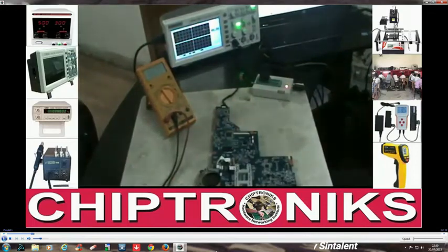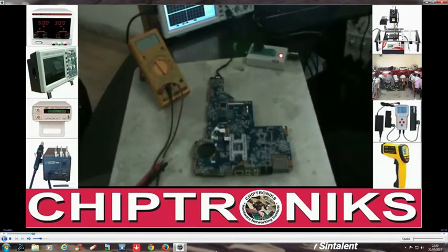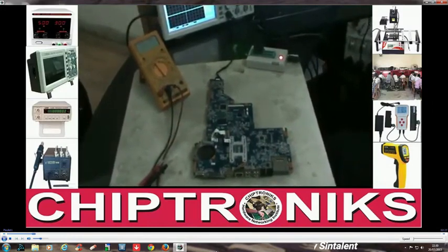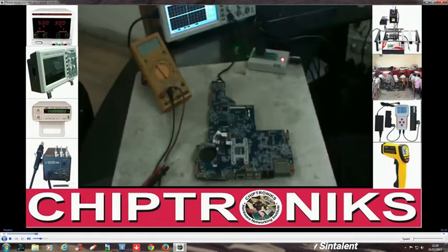Some kinds of motherboard which have a PCH IC have two BIOS ICs. One is the EC BIOS and the second one is the system BIOS. EC BIOS is always connected with the IO IC and system BIOS is connected with the PCH.